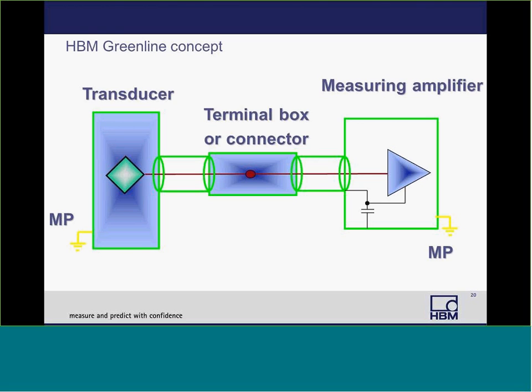All the components in the chain need to be surrounded by a closed EMC tested shield. And the shield transitions should be solid and realized in the form of flattened, closed, and low impedance joints. And this is ensured if you use original HBM connectors.